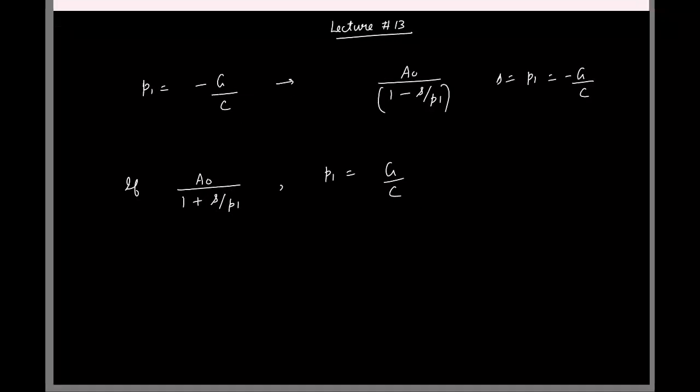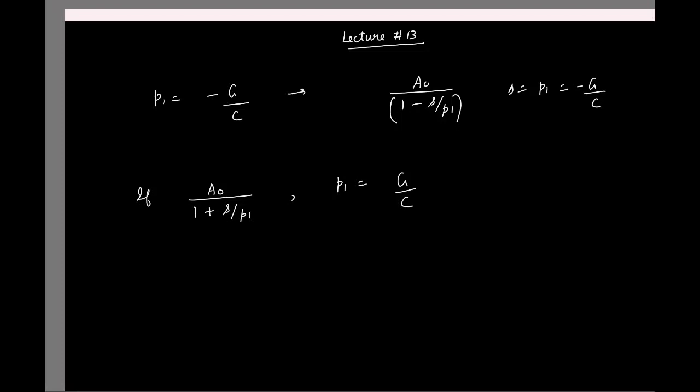Cool. So in the last class we were looking at the issue of instability in negative feedback, and the motivation was the following. We saw all our single stage OTAs can be modeled approximately as a first order system because it has one dominant pole. But what was the problem with single stage OTA? It cannot drive resistive loads, so that's why we decided to cascade multiple such stages. But then we saw each stage will have its own dominant pole, so overall you have a higher order system, so it can be unstable. So that led us to this path to understand stability,